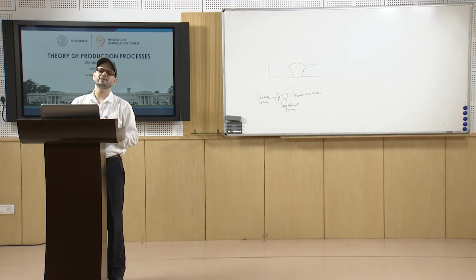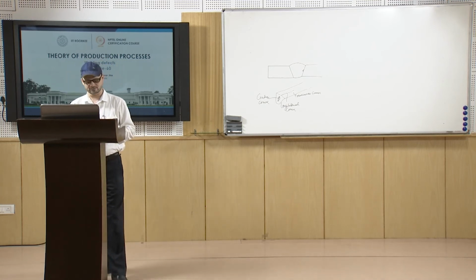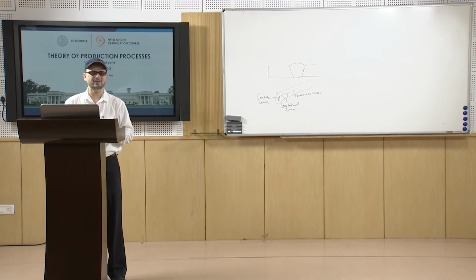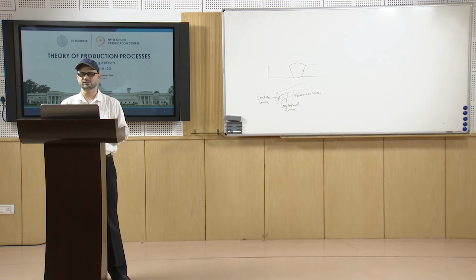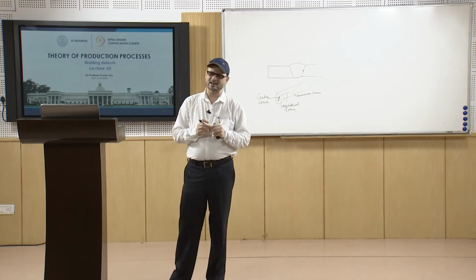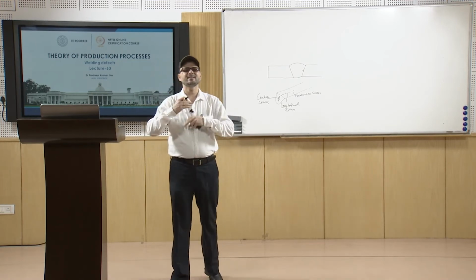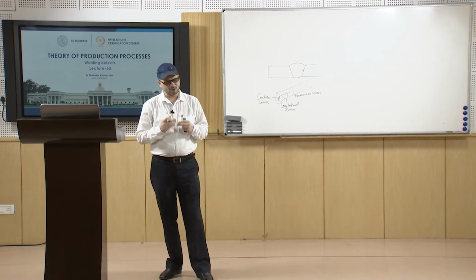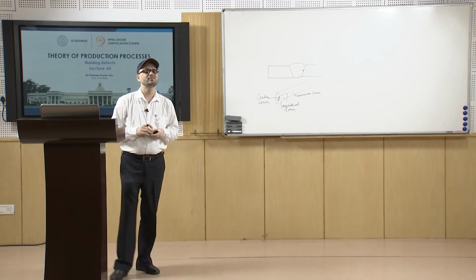Many a times we get an incorrect weld profile, and that also has a remarkable effect on the weld quality. It mainly happens that when you give the first pass and that pass is not proper, in those cases the weld profile may be improper.